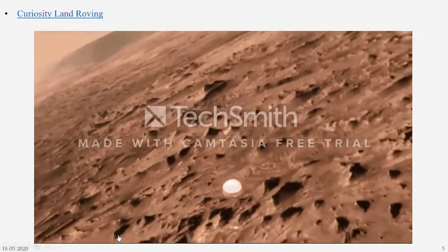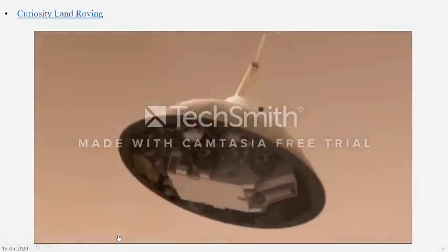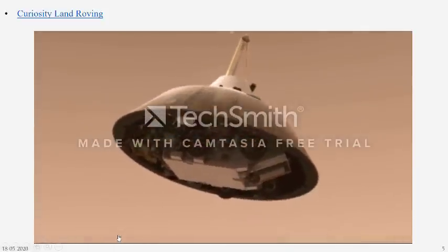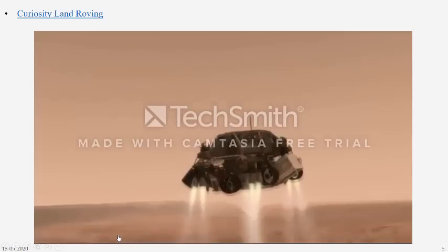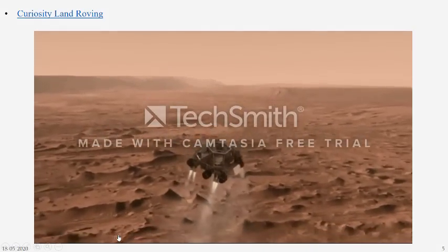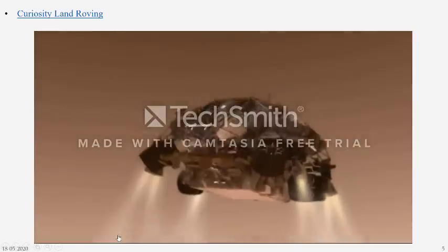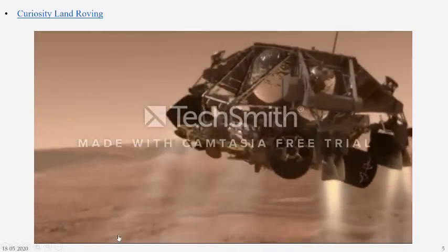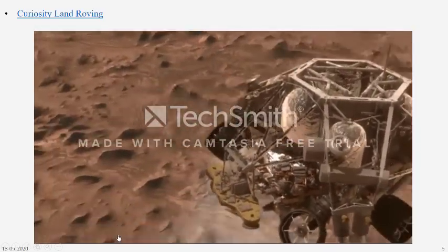force. But now, I have for you some more scary news. Because the Martian atmosphere is so thin, the parachute isn't enough to achieve a safe landing speed, so, you guessed it, a third stage is necessary: the powered descent. The parachute detaches and the falling craft is caught by retro-rockets which slow it further, jetting it away from the parachute so it doesn't get tangled up, and eliminating not just vertical but horizontal speed.